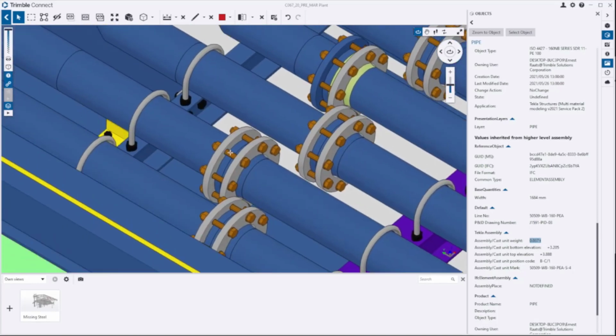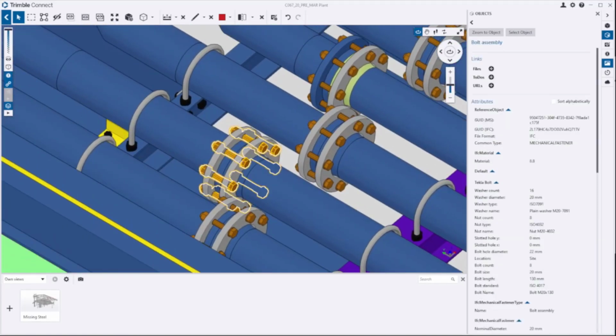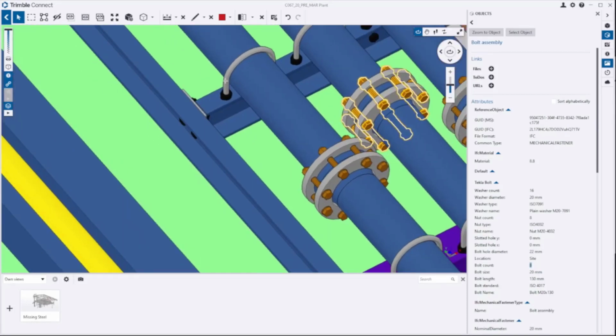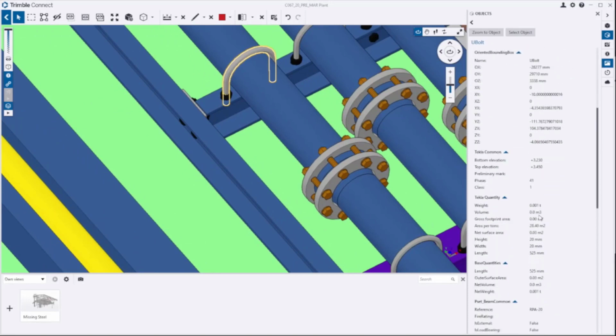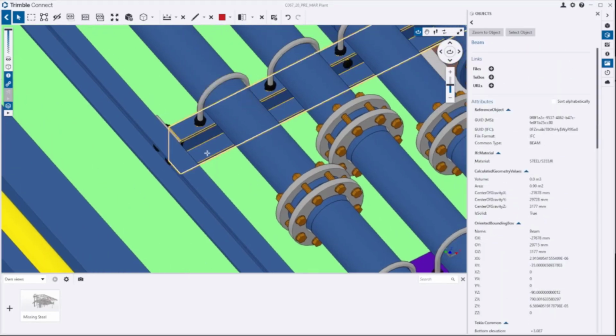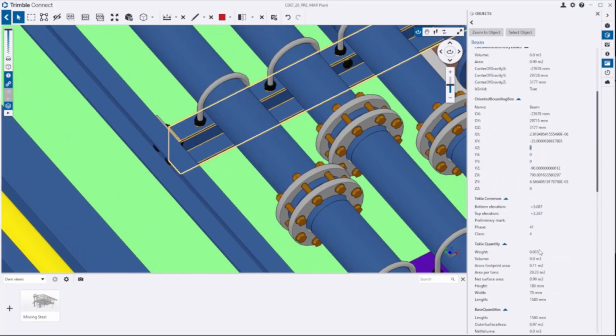Also able to distinguish what bolt sizes we need to use between two flanges and the quantity of bolts. We've had it a few times before where people use all the long bolts before they use the short bolts, and then you get to the end of the project in the middle of Tanzania and you have to ship thousands of bolts up to site.